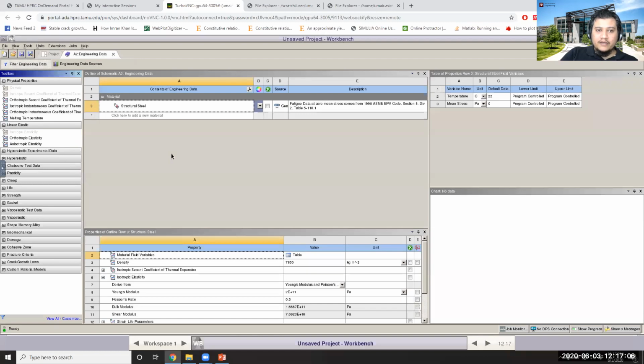But if some of you are modeling composites and the like, for example wood or CFRPs, you may need to use the orthotropic elasticity. If you are doing something on the grain level, you know that metallic grains and even ceramic grains don't have isotropic elasticity, rather they are anisotropic. So you may want to use the anisotropic elasticity for those kinds of cases as well. But for today's problem, my plate is made out of a material which has isotropic elasticity.